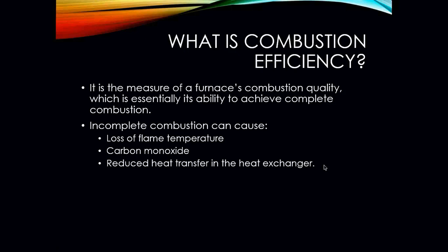What is combustion efficiency? Well, combustion efficiency is the measurement of a furnace's combustion quality, which is essential in its ability to achieve complete combustion. Incomplete combustion can occur when we have a loss of flame temperature, when we have carbon monoxide, or when we have reduced heat transfer in the heat exchanger.